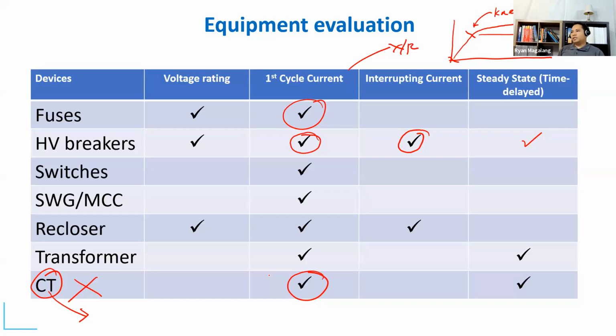Did you say residential and commercial? I think it's like a mall, mixed-use tenants, it could also be office spaces. So, industrial facility, sorry. For an industrial facility, we normally estimate 80% of the load to be motors. Based on that, you can estimate how much fault current it contributes.